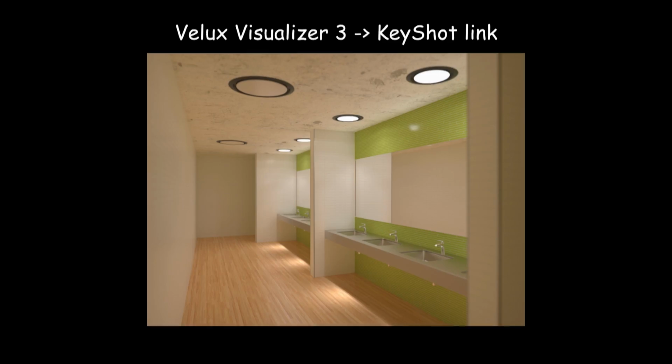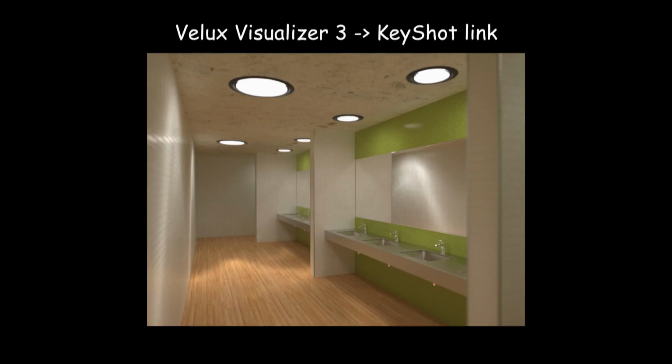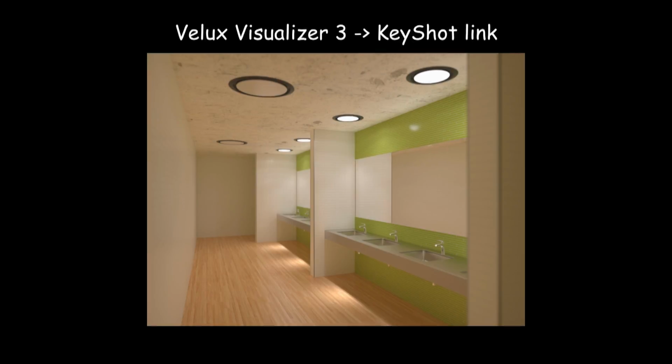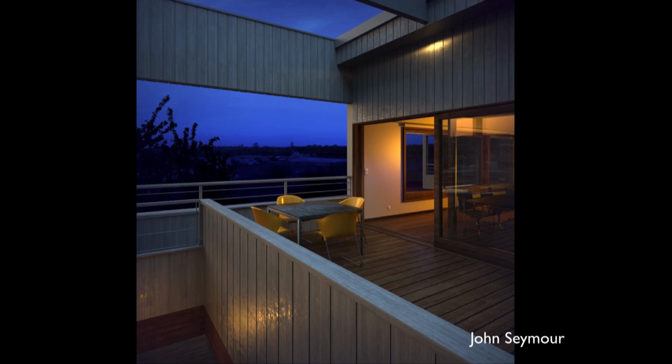I guess you'd have to go back and do the lighting simulation again if you change the materials too much, because, of course, it all works together. And then here's just an example where we asked, what if you don't rely on the sun tunnel, but you rely on electrical lighting? So we use some standard IES lights up here instead. So you can just play with that, have different types of lighting in the scene. And then you can use it, of course, for other architectural spaces as well.